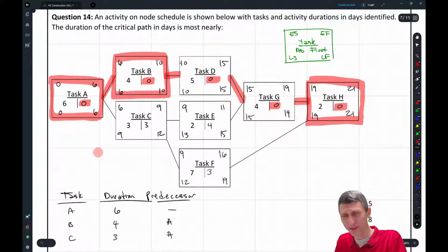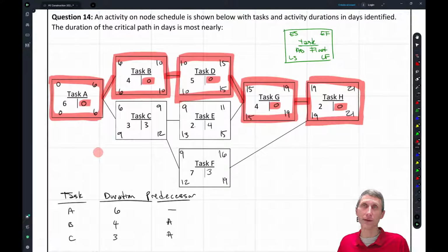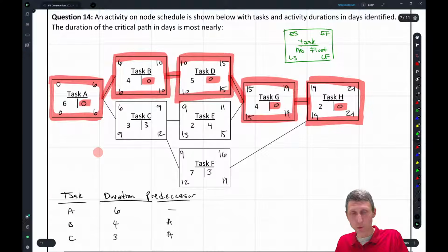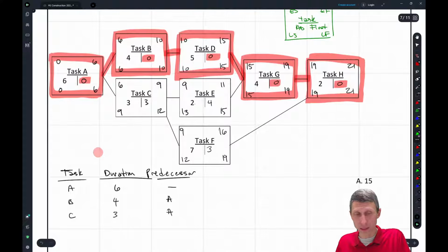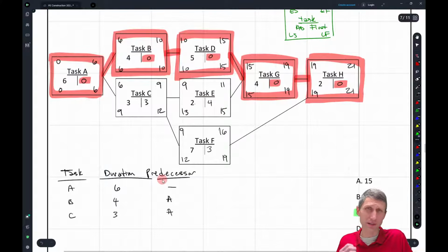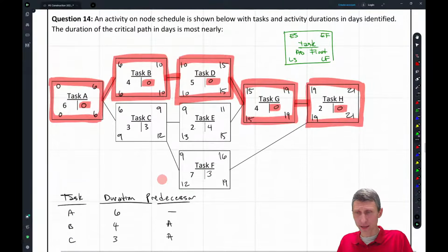And you might be given a conceptual question about this. I wouldn't be surprised if you get some network precedence diagram like this that you have to either fill out or complete or do something with. But identifying the critical path looks at which ones have 0 float, can't be moved, and still maintain the same schedule. But this gets into some of those task durations, predecessors, those types of things as well. All right, hopefully that's not too crazy and makes a little bit of sense.